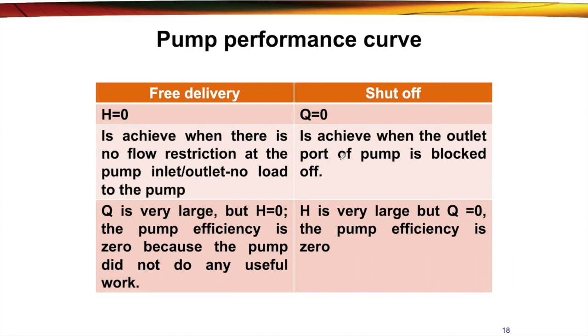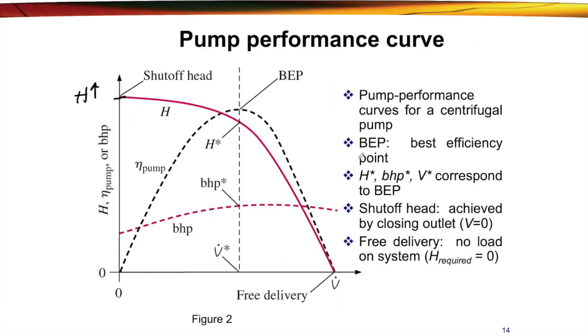So what will happen? It will increase the head of that system. That's why the head of the pump at this point on the graph is at its highest when the pump is being blocked. The pump is still running, but Q is 0. There is no fluid flow into the pump.